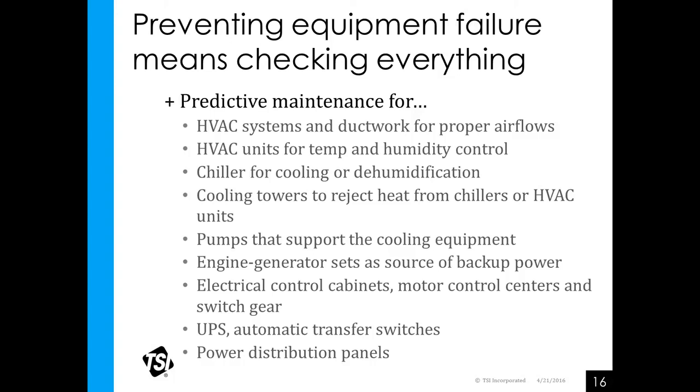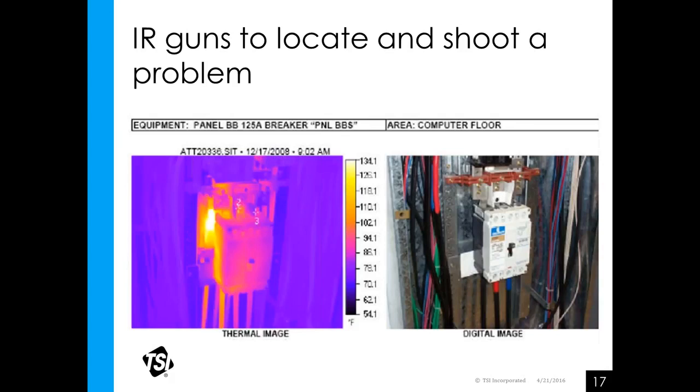Is my critical HVAC system about ready to be shut down because of a faulty fuse or a hot spot or whatever? So here's a contrast between the thermal image. Here's your hot spot. You can't see it in visible light, but some non-intrusive techniques are now part of the critical HVAC arsenal of weapons that an HVAC tech would probably be using. I keep saying require a higher level of instrumentation, and that's true.